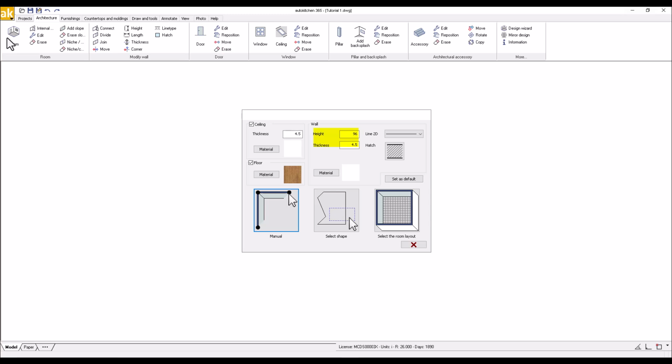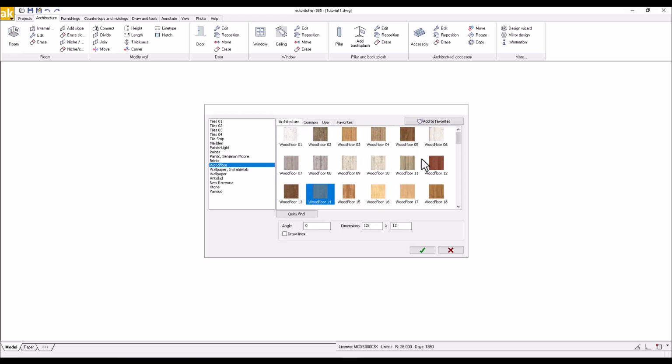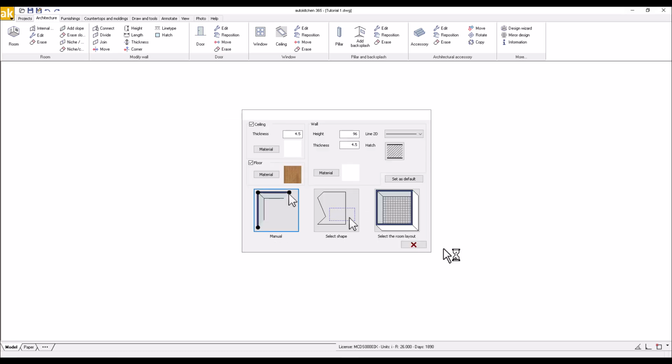These values can be changed by entering different numbers in the corresponding fields. You can also customize the paint color for the walls and ceiling, as well as the flooring material. To do so, simply click on any of the default selections and choose from the available options. When drawing the room, use your mouse to indicate the direction of each wall. Use the numeric keypad to enter the interior dimensions of each wall segment. As you proceed, the drawing direction will generally move clockwise.